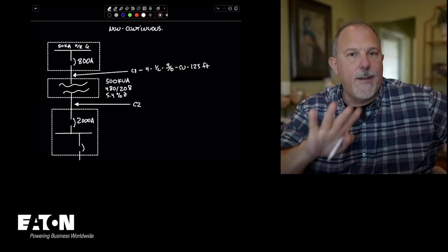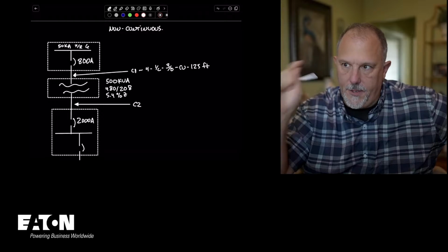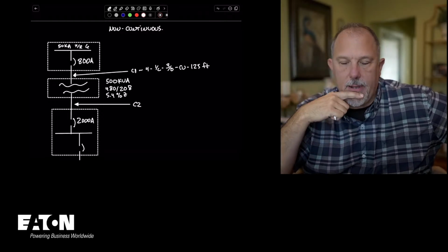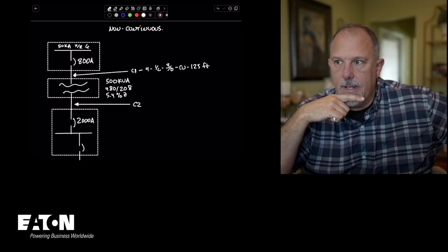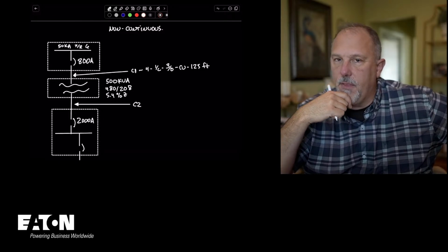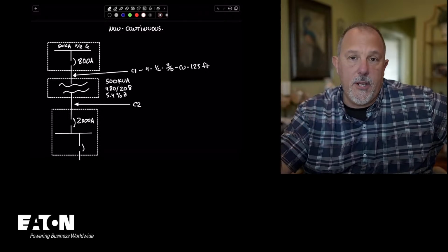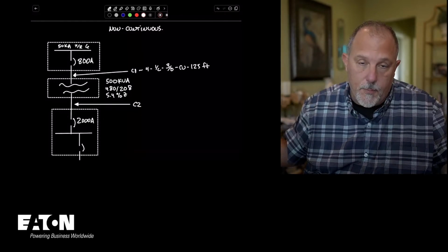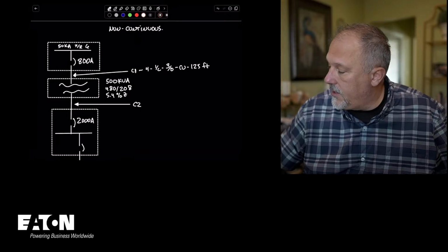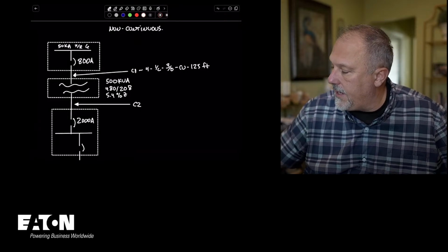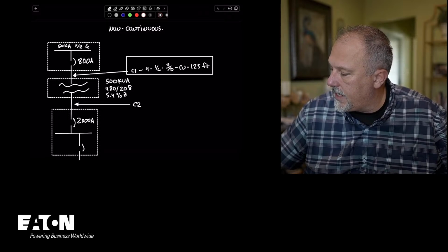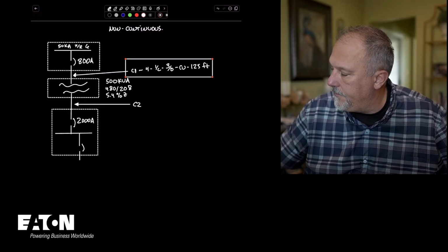That would be 800 amps worth of conductor on the nose. And I think 3/0 conductor is probably easy to work. Would you agree with the 3/0? And then let me know if 125 feet is reasonable. I mean, we're doing math, so I can make that any length I want to, but I am going to say that is my conductor number 1.